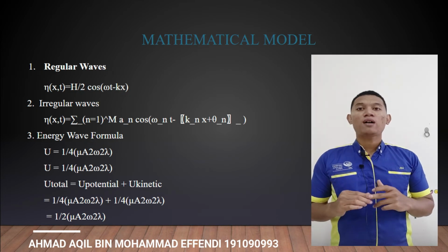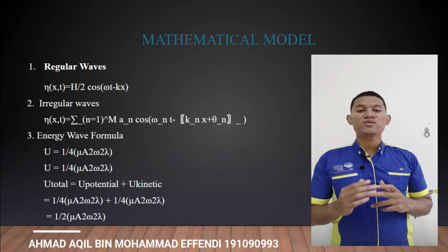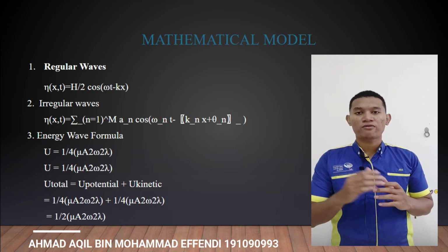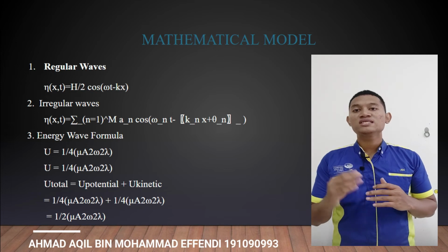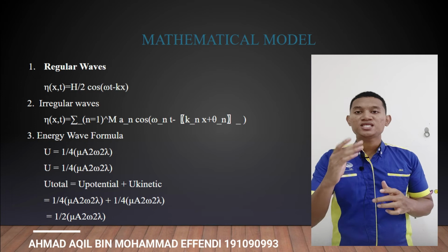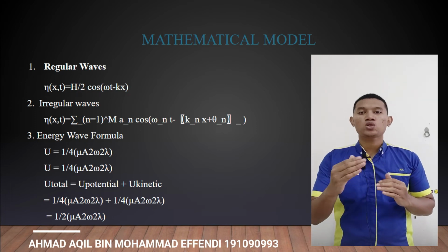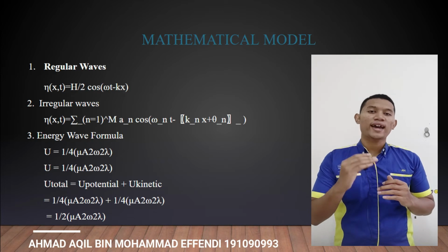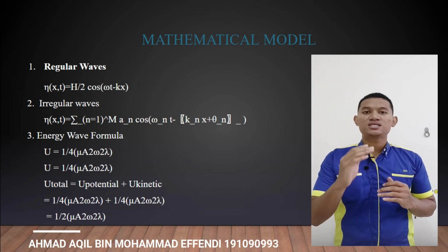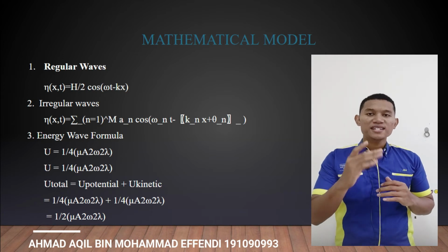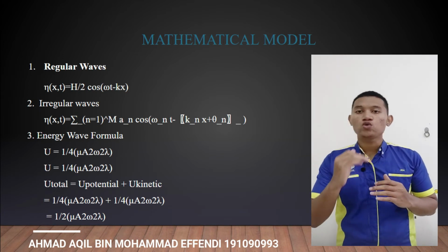The elevation of an irregular wave is expressed as a sum of waves that come in different shapes, in the equation you can see in the slide, where m is the number of added waves altogether, a is the amplitude of the wave, and φn is the phase shift of the nth wave, which takes a value from 0 to 2π.